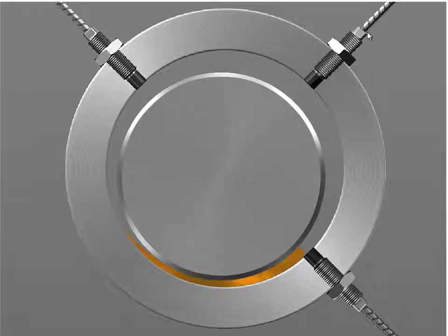So we use these proximity probes instead. These two probes are sensitive to the distance between the tip and the shaft. As it moves in this direction, this one picks it up, moves in that direction, this one picks it up. We use it to triangulate. These two probes are mounted 90 degrees apart, and we kind of triangulate the motion of the center of the shaft. I'll explain that a bit more in a second. The third probe here is not in the same plane as these ones. This one might be at the end of the rotor or somewhere where there's a key or keyway, and it measures that displacement, and that gives us our once per revolution information.